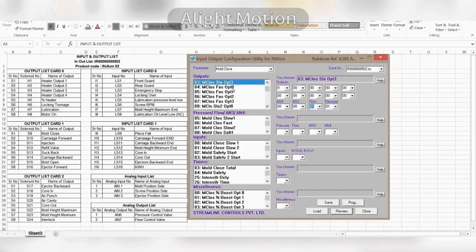Accordingly, mold close fast option 0: output number 9 and pressure 0 1 and flow 0 1 enable. Same way, mold close fast options 1, 2 and 3: output number 9 and pressure 0 1 and flow 0 1 enable in each.